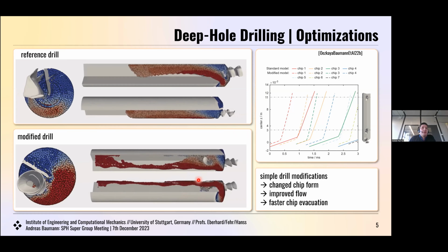Now I talked about a bit how we apply that to actually improve the design of the models. The next step is we want to investigate this phenomenon of chip jamming in the process. So we tried first of all to replace the rigid chips by an SPH solid application of the chips. So we apply SPH also to model the solid equations of motions for continua for this chip. So we placed also some SPH particles here, and we added an artificial barrier right at the end to get a first modeling of our chip jamming.